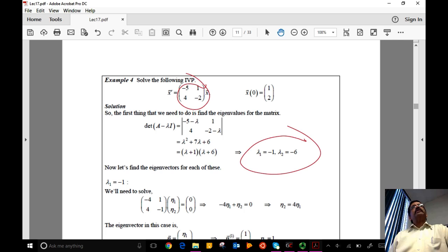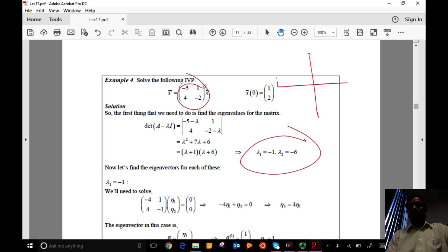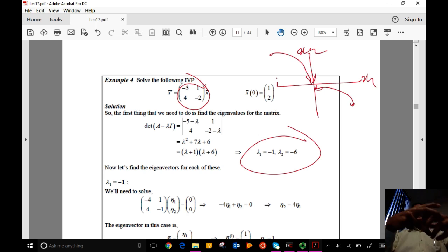So how do you think that state space representation will look like, the trajectories? Of course, where the two eigenvectors lie, you need to solve for the eigenvectors. Then you can sketch whichever way the two eigenvectors are, the orientation of the eigenvectors. But if it's a stable mode, no matter where you start, it's always going to be attracted like that towards the steady state.